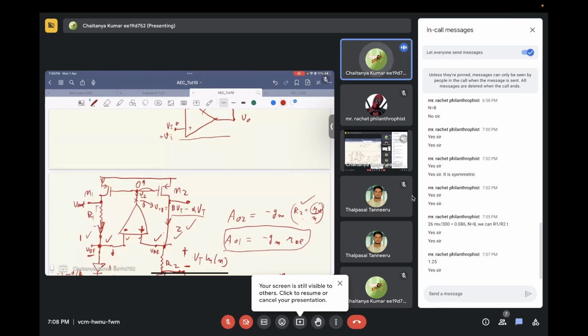If you keep on increasing the value of R2, then the physical realization of R2 might not be feasible. So you need to choose the maximum value of R2 that is possible in your technology to make the band gap reference generator. You understand? And once you choose the value of R2, your value of R1 gets fixed based on the principle of the band gap reference generator.